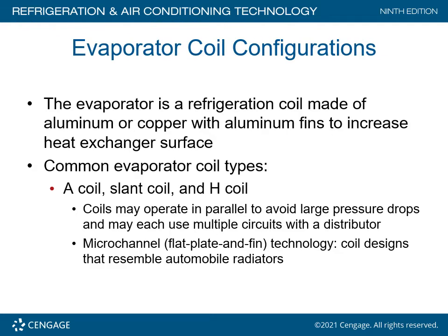Evaporator coil configurations. The evaporator is a refrigeration coil made up of aluminum or copper with aluminum fins to increase heat exchange surface. I might add a footnote on the new evaporator coils. For most systems I'm installing currently, they're all aluminum.